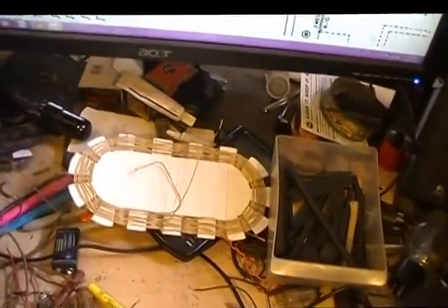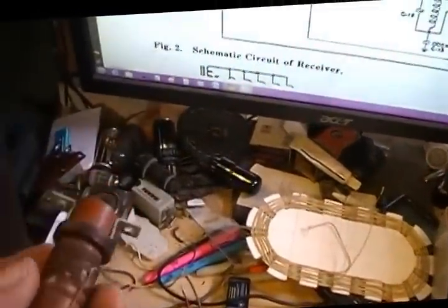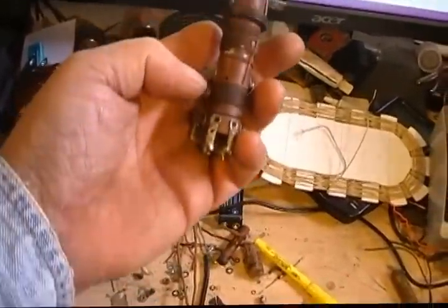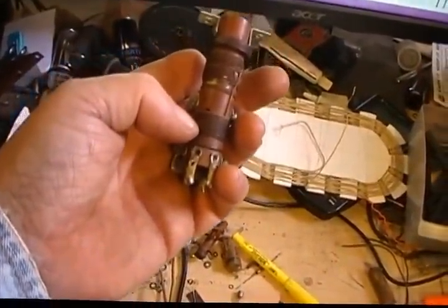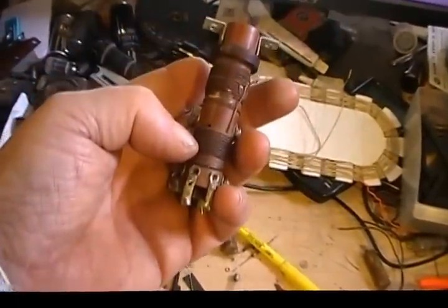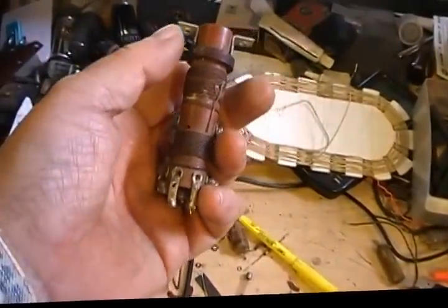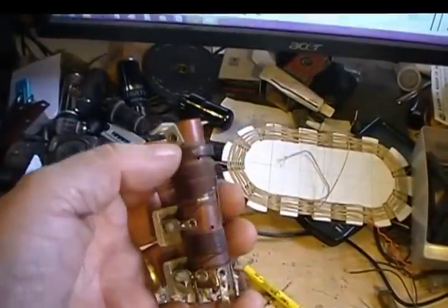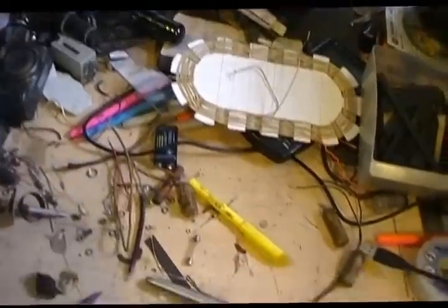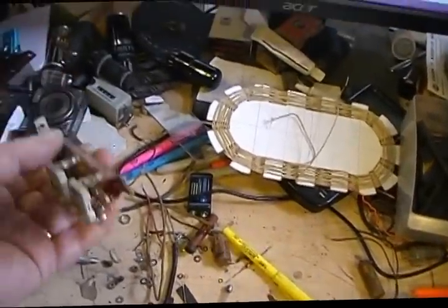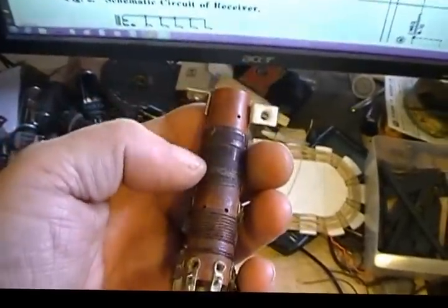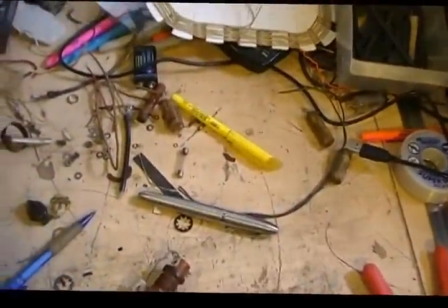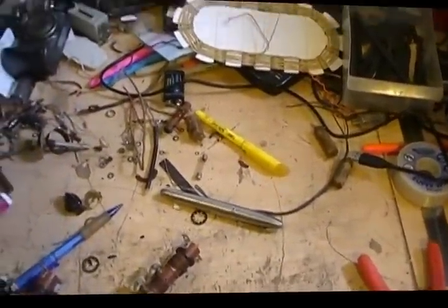Your antenna coil is going to have more windings. This end of the antenna coil represents the broadcast band. This is this end here. These coils represent the shortwave, and this actually goes up to about 18 megahertz. So anyway, on the broadcast band, you can see that it's got a lot more windings on it as opposed to the oscillator coil, which is the broadcast end. It has a lot fewer windings. So that's how you tell the difference. That's the number one thing, to find the difference.